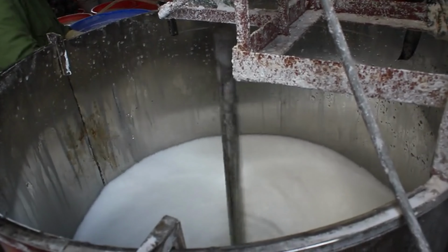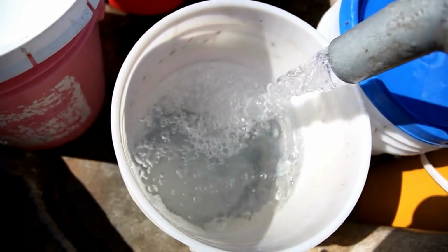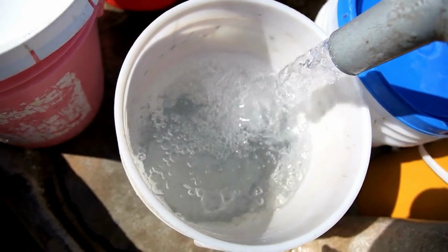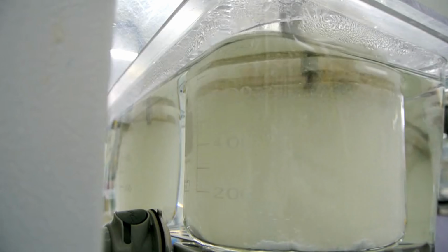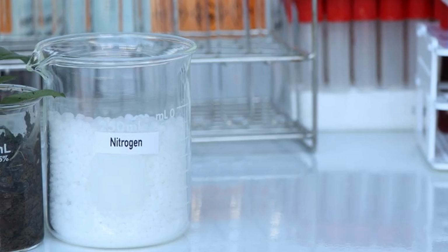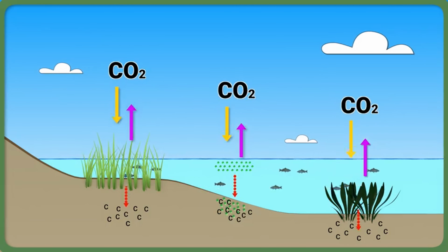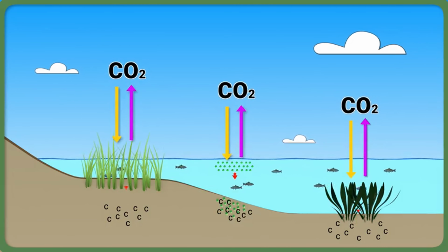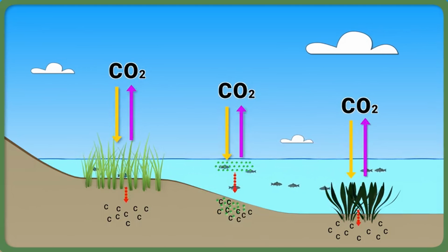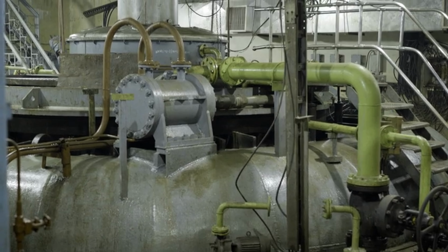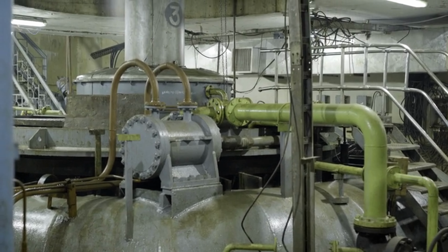Modern bleaching methods. Elemental chlorine-free, ECF, bleaching uses chlorine dioxide. Totally chlorine-free, TCF, bleaching uses oxygen, ozone, or hydrogen peroxide. Oxygen delignification reduces the need for harsh chemicals. Environmental concerns and solutions. Old chlorine-based bleaching created toxic dioxins. Modern mills use closed-loop water systems to recycle bleaching chemicals.